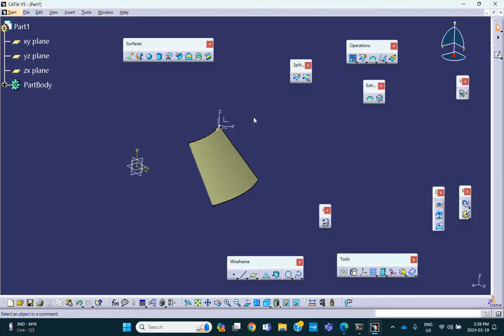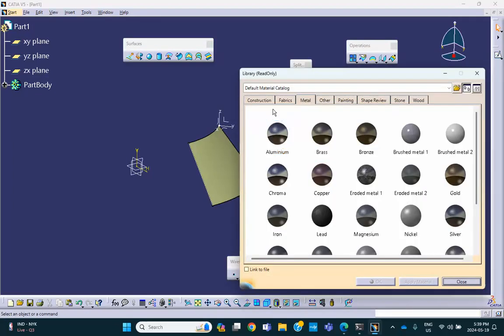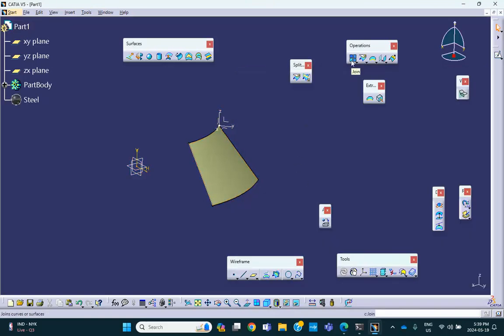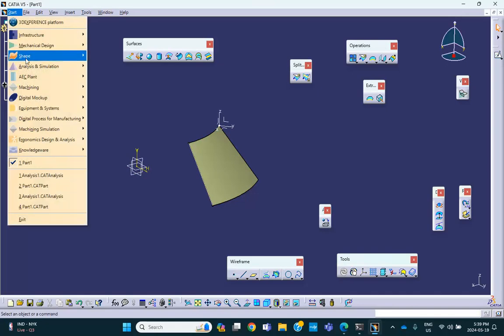of that system. Okay, let's apply material properties to this. So I think it's steel. The problem says it's steel. So we do it like that. I don't have to join this thing. You can join it, but you're not going to gain anything if this is a single surface, which doesn't require a join. Now if we do the fancy mesh, we're going to go to the advanced meshing tool,